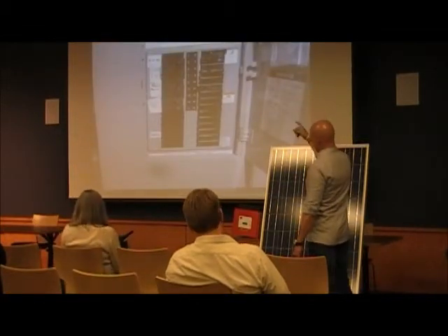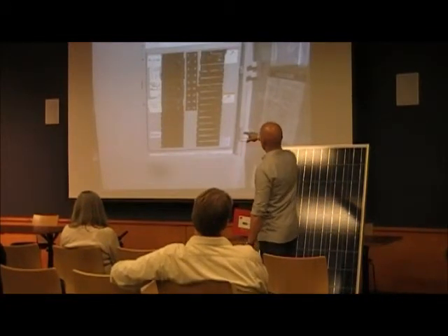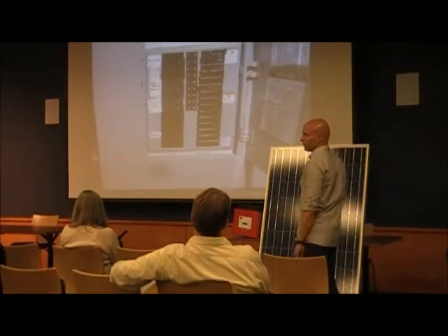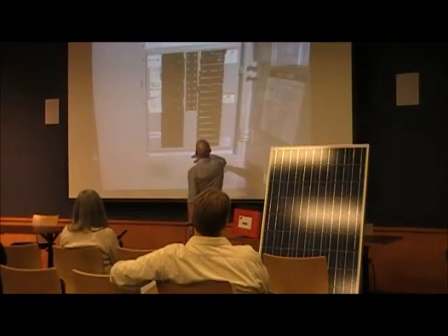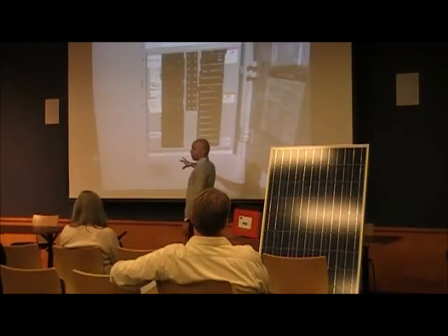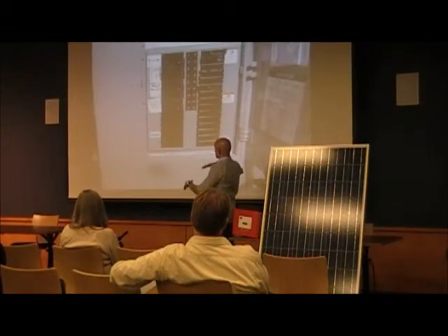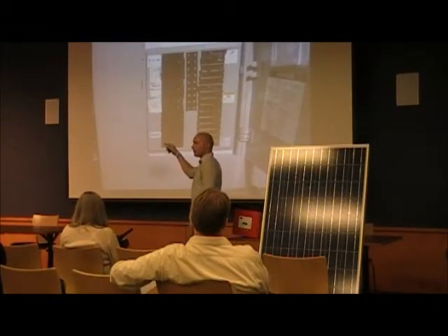Okay, then off this inverter and off your AC disconnect, it pops right into your, and everybody has one of these, your main service box. When we're looking at installing, we like to see empty spaces. This is a bus bar right in here. So you look at bus bar spots, and we'll get an idea of what voltage this is. Is it a 208, 240, which is your homes? Is it a 480? We'll design these systems on certain inverters that need to be in certain voltage ranges. Once we go out through the DC and the AC disconnect, we pop into the main service box, and that either goes into your house or it goes out to the grid.